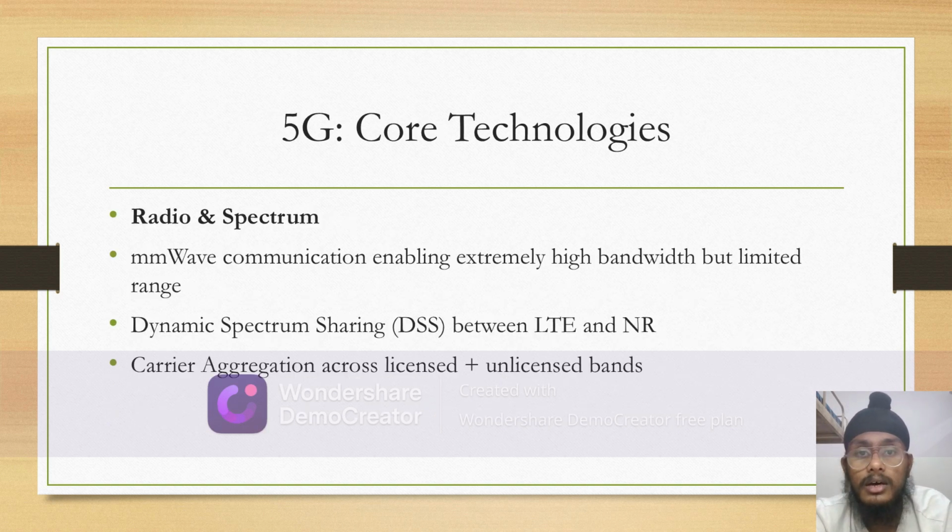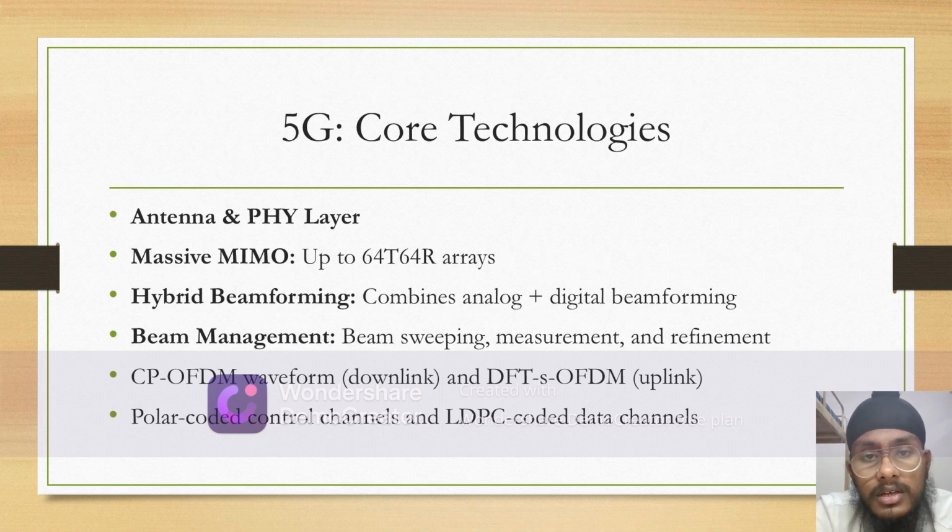So in the another slide, core technologies of 5G is continued. The points that come under this are antenna and PHY layer, massive MIMO, hybrid beamforming, beam management, CP-OFDM waveform, and DFT-OFDM. And the last key point is polar coded control channels and LDPC coded data channels.